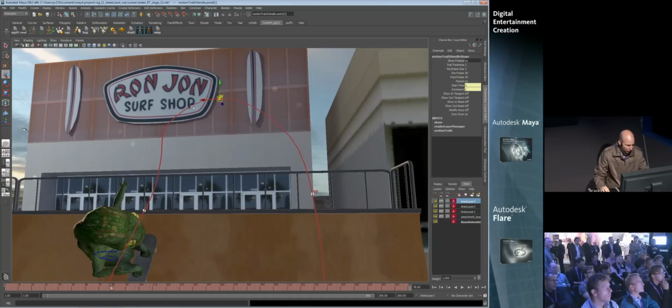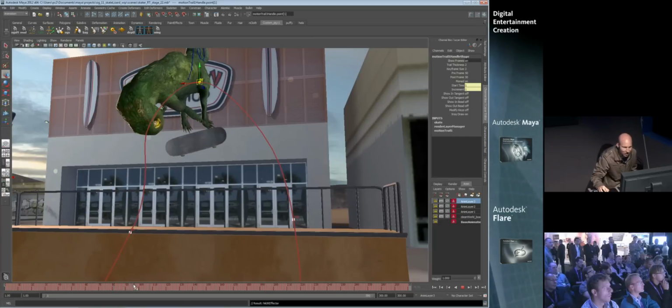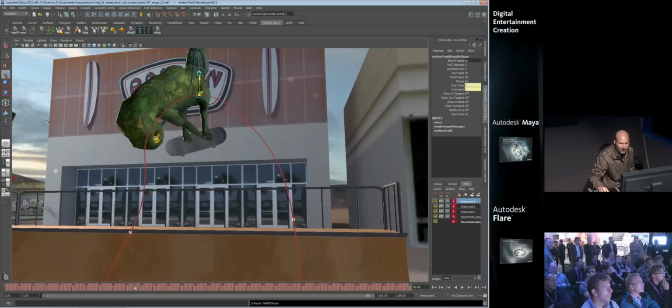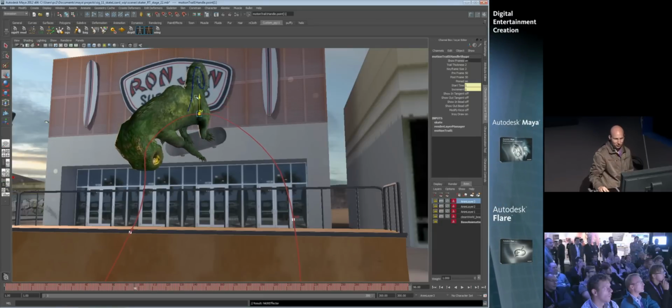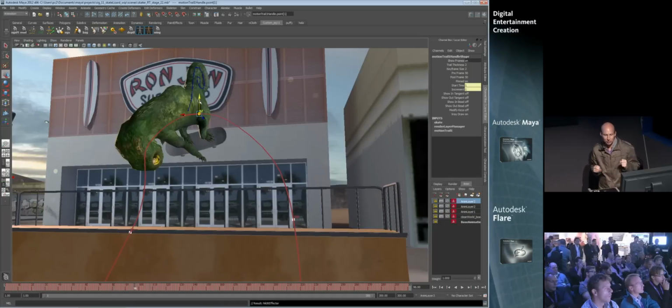That means I can grab a keyframe on that motion trail and edit its position. You notice that it's just given me an offset, but I still have that really nice, subtle movement inside of there. It's also worth mentioning, this is being done on the HIK solver, so notice the effect. His feet will hit that skateboard when I compress him back down. The power of combining HIK with editable motion trails is significant.